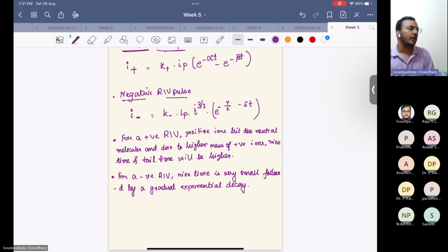Before that, what is the main issue with this RIV? When the RIV signal frequency matches with the frequency of the transmission line or the power frequency, the interference signals will overpower these RIV signals, which can cause disturbance. Thus, it should be noted that these transmission lines should not generate RIV at all, or even if they generate RIV, it should be well within controllable limits.